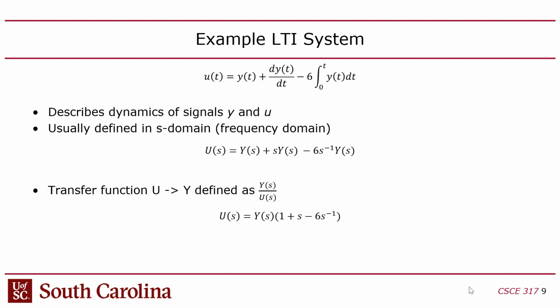See, this doesn't really have outputs and inputs. It's just a function, right? But if you create a transfer function, you have to rewrite it where the output is in the numerator, so the y of s in this case would be the output, u of s is the input, and that's the denominator. In order to restructure it into a transfer function, you're just using algebra. So you factor out y of s over here on the right-hand side of the equation, and you divide both sides by y of s.